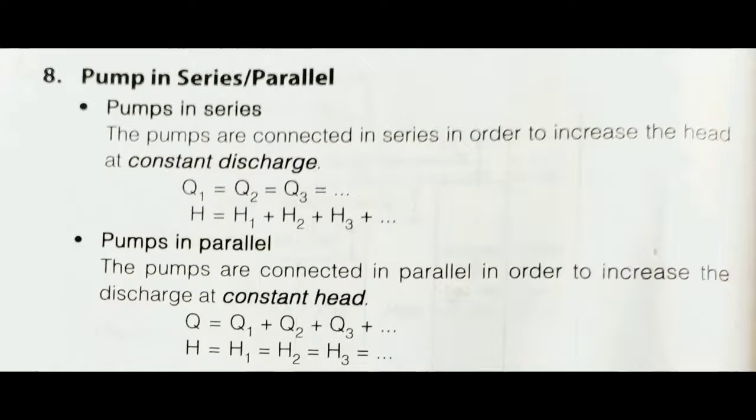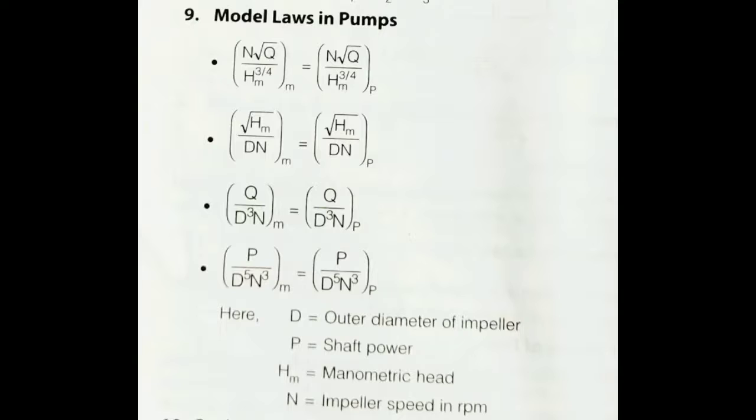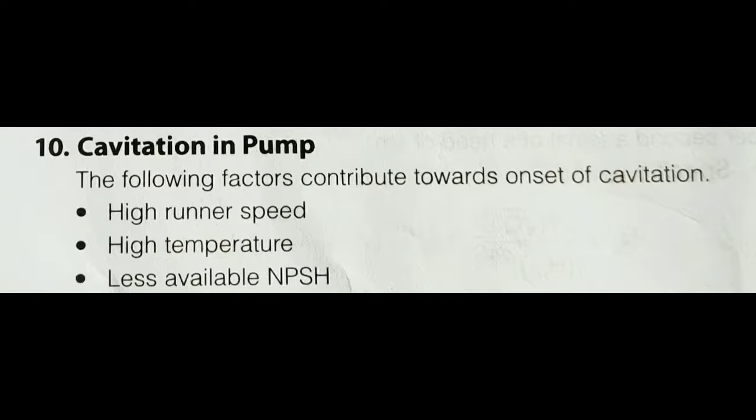Model laws in pumps are the same as those of the turbine. See these equations. Remember these equations by heart. Very important. This is cavitation in pump. The following factors contribute towards onset of cavitation: high runner speed, high temperature, and less available NPSH.